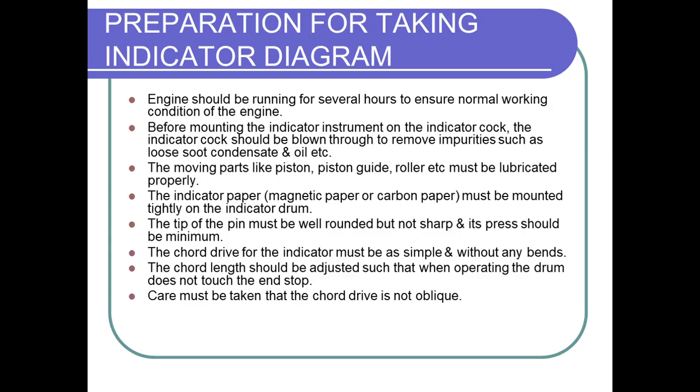Before mounting the indicator instrument on the indicator cock, the indicator cock should be blown through to remove impurities such as loose soot, condensates and oil, etc. Under normal working condition, we are going to the maximum speed, and as per load condition and sea condition, the ship has to be in loaded condition. These are prerequisites that we take into account.